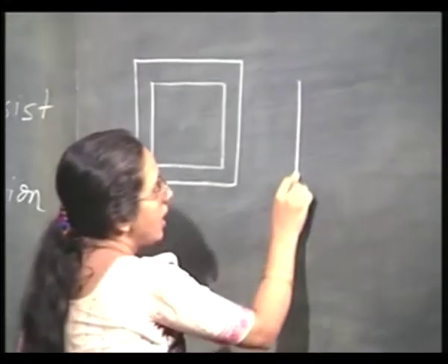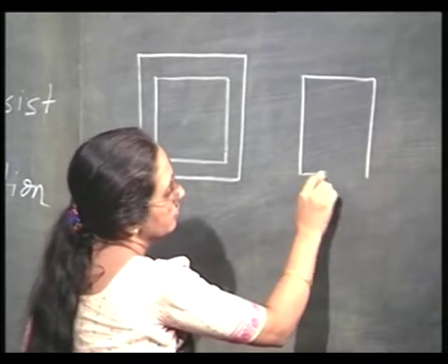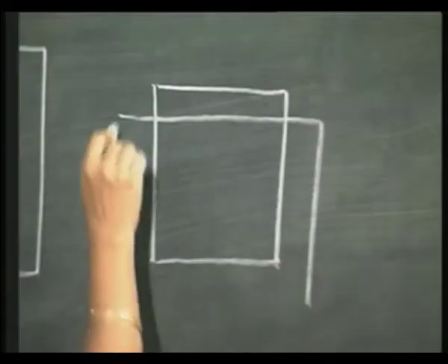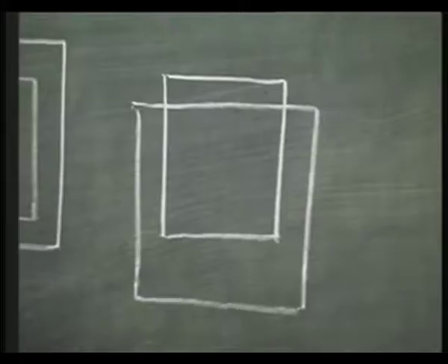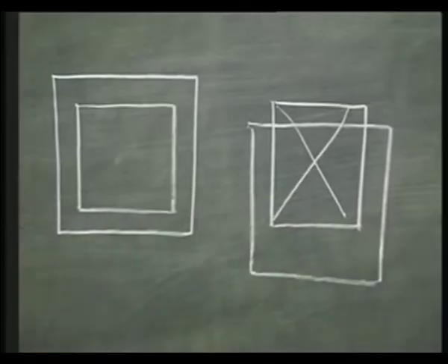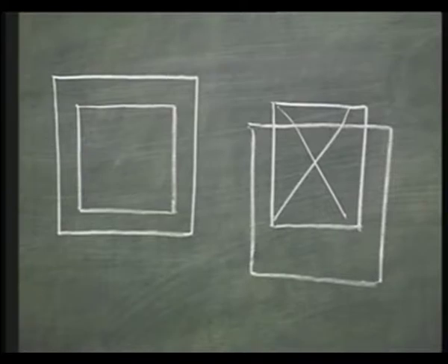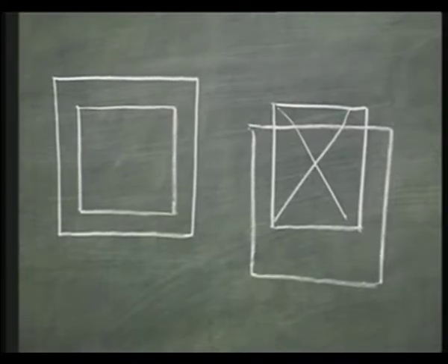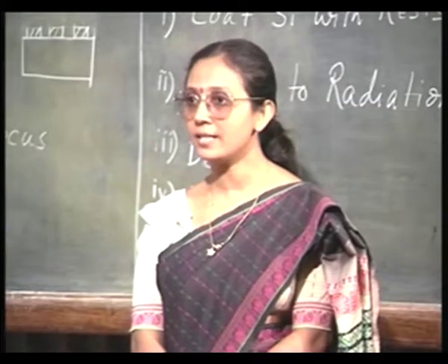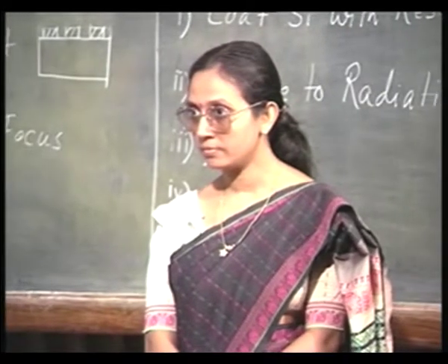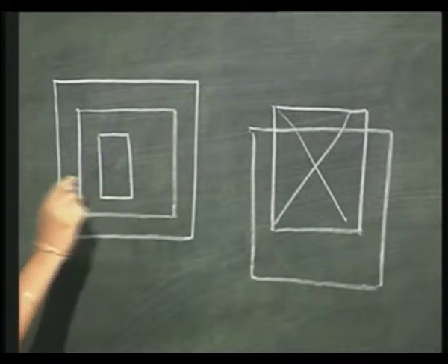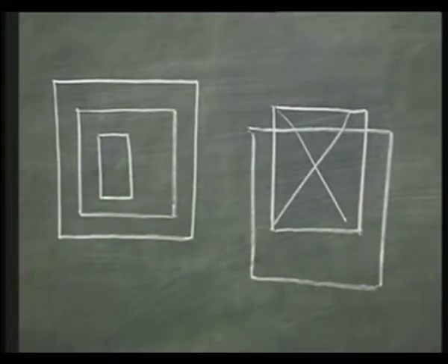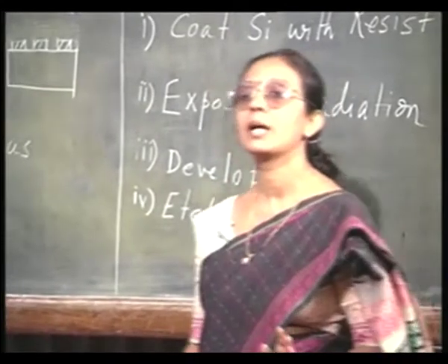If, however, I have pulled it down, I cannot have it, right? I must ensure that mask number 2 is aligned to mask number 1. Similarly, my base diffusion mask must come inside the active region and should not spill over to the adjacent regions. Agreed? So, all these masks must be aligned to each other.